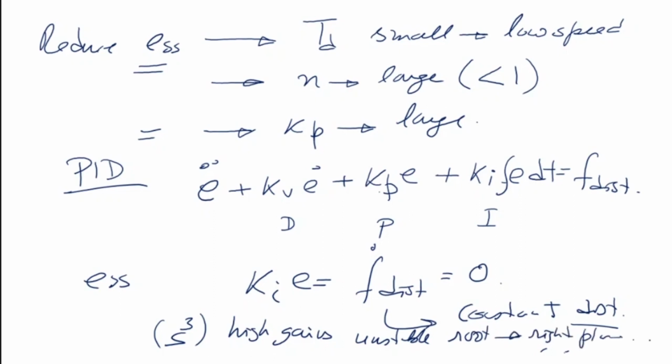So this is the basic theory of PD controllers and PID controllers. Although PD controllers have some steady state error, it can be made small by looking at these 3 things. And that is the reason why PD controllers are used even in industries. Whereas PID controllers give you 0 error, which is good, but then it involves other problems, because of the high Ki gains. If your gain Ki is very high, then there is a chance it will become unstable. And because you're integrating now, it involves some kind of a time delay.